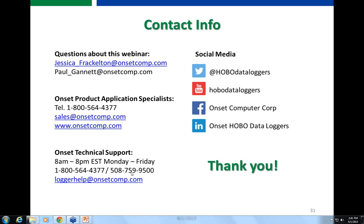But for things like changing the logging interval, setting up an alarm, setting up the data delivery, or configuring an analog sensor with scaling, you would be required to go through HoboLink with an internet connection, either an internet-enabled laptop in the field or a mobile device, or you can reserve that activity for when you're back at the office and do it from there. Is that a good answer, Paul? Yep, you explained that well.